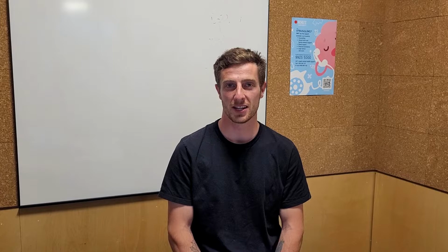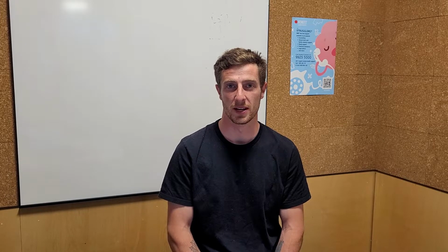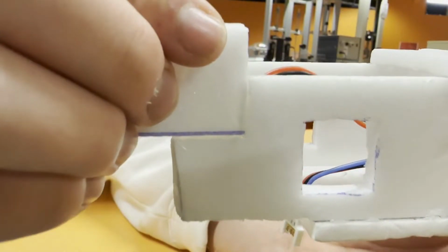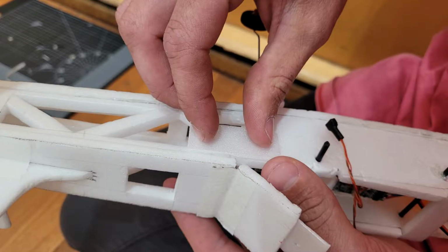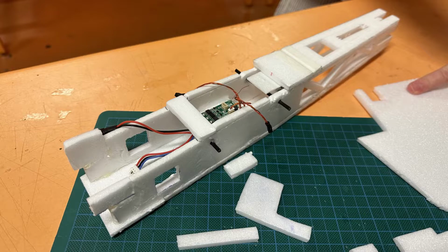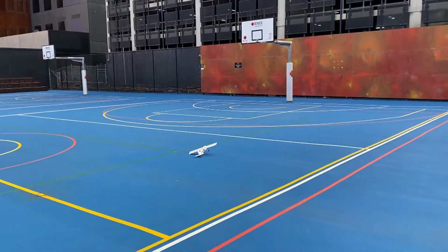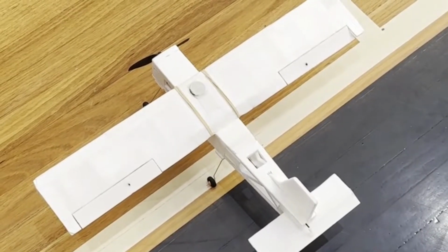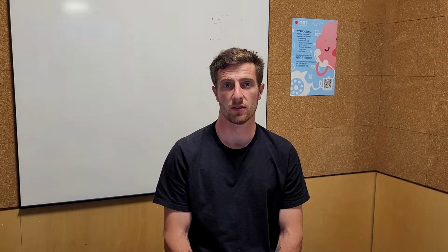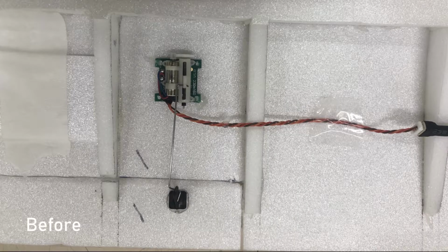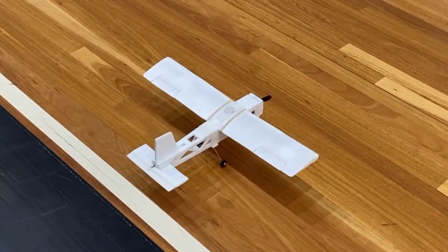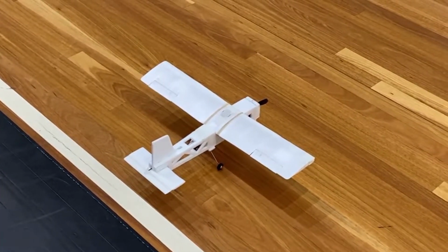Over the course of all the testing, there were several instances where repairs needed to be made. Sections of the fuselage needed to be replaced where they had been ripped off or cracks had appeared in the foam. Thin layers of foam were added to parts of the wing to reinforce them. The wing tips were damaged from scraping the ground. The rubber bands that held the wings on also had creased the frame at the wing root. The servo motors under the wings fell off a few times, so we decided to attach them to a smaller piece of foam. This was taped to the underside of the wing. Whilst protecting the frame from ripping, it also provided some adjustment to tune the resting midpoint of the ailerons.